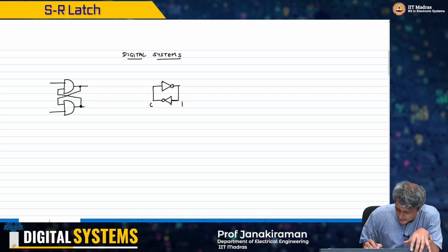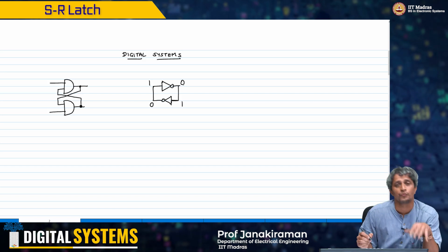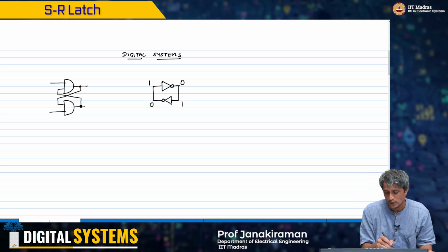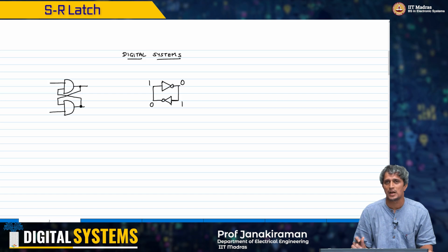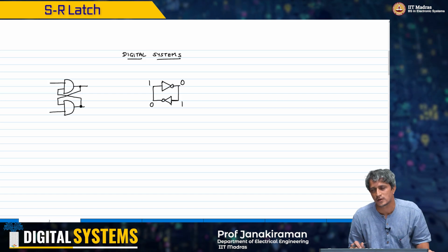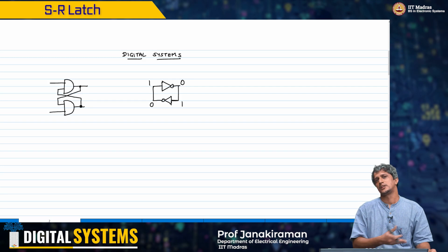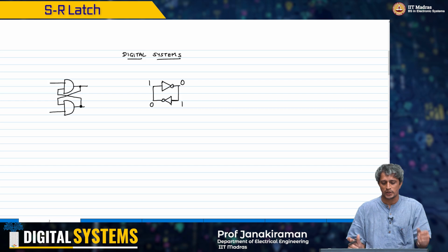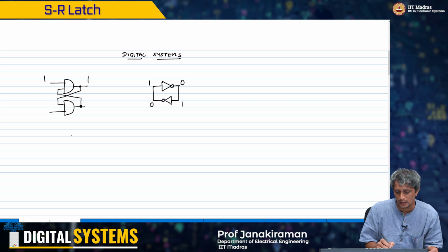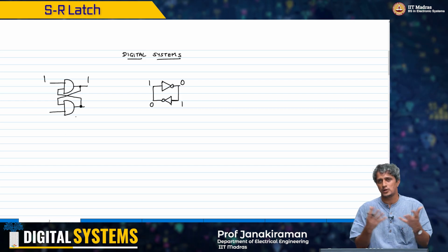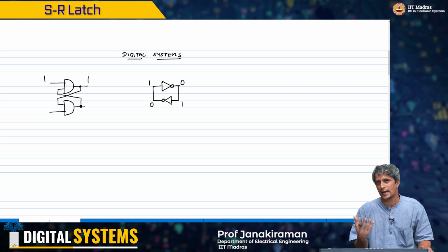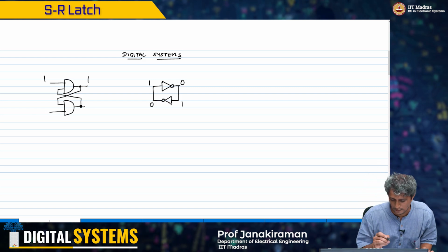So this back-to-back state is very important, and when you don't have an inversion available, like in the case of an AND gate or an OR gate, this whole back-to-back connection makes no sense. If the input is 1 here, then the output has to be 1 here, and there's no way that you can hold that state. So the inversion is very important in order to hold this state for us.